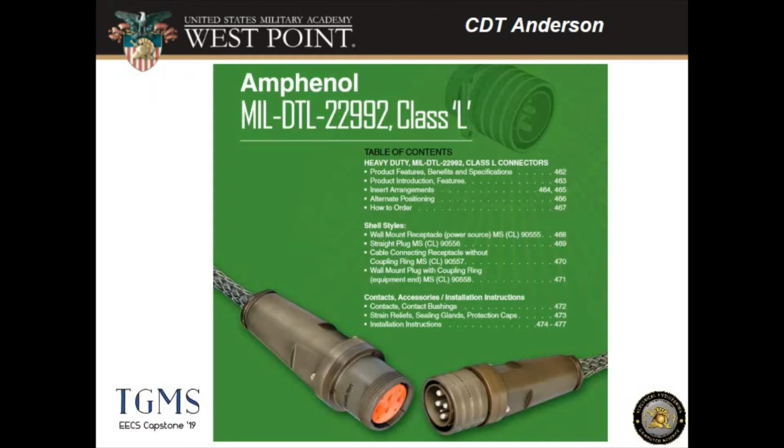In terms of connectors, this helped us choose the connector that had a max capacity closest to 50 amps. As per Colonel Shea's recommendation, I looked at the MIL-DTL-22992 Class L connector manual to find the connector that would be best for the design.